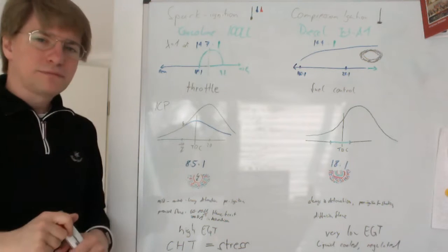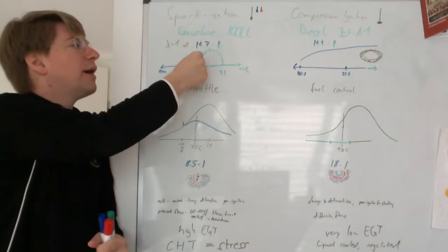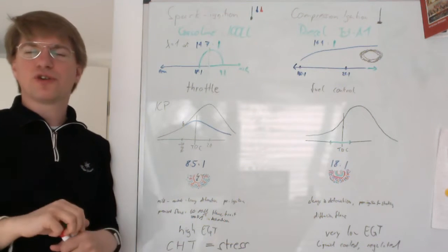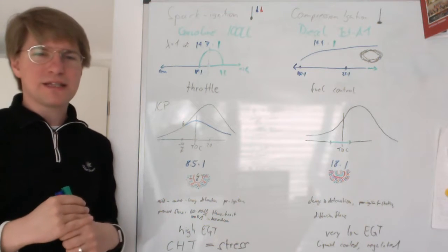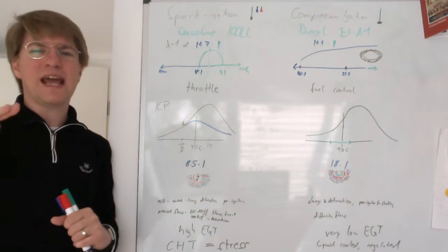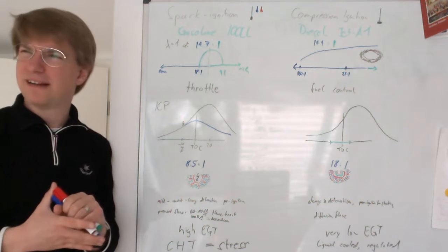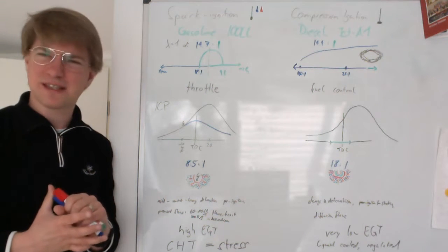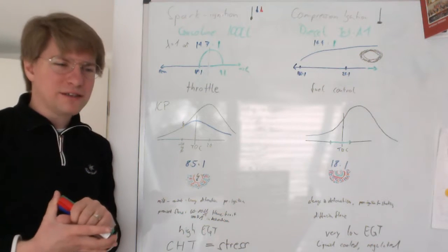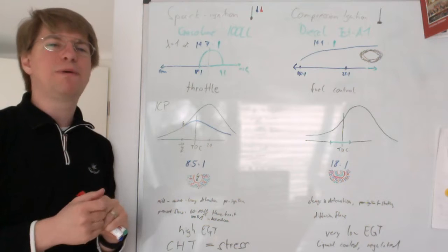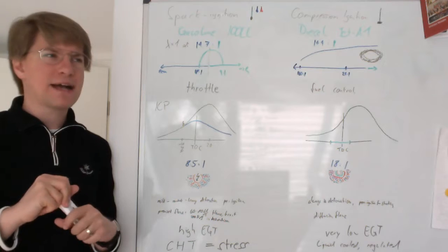All right, so suppose we are at less than maximum power, and we have set the mixture control optimal for our altitude. What is optimal? Well, that depends on your mission. If you are taking off from, let's say, the Grand Canyon National Park Airport, which has an airport elevation of, I don't know, 8,000-something feet, it's high. At this point, the optimal mixture you want for takeoff is the one that gives you peak power. So you lean out the red knob to give you the absolute maximum power.